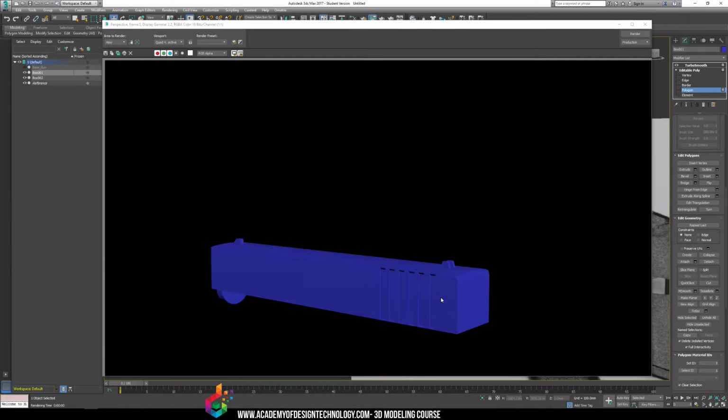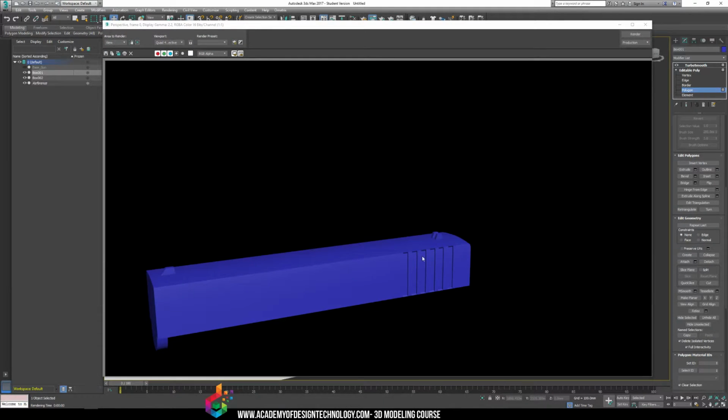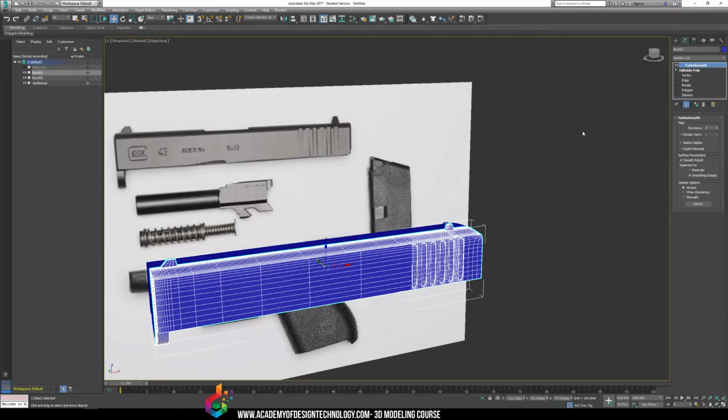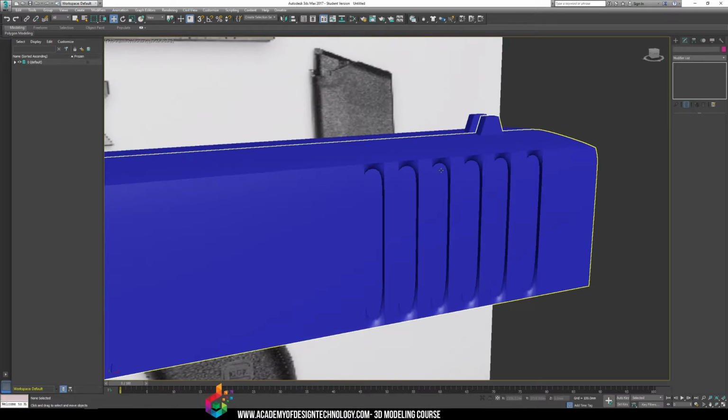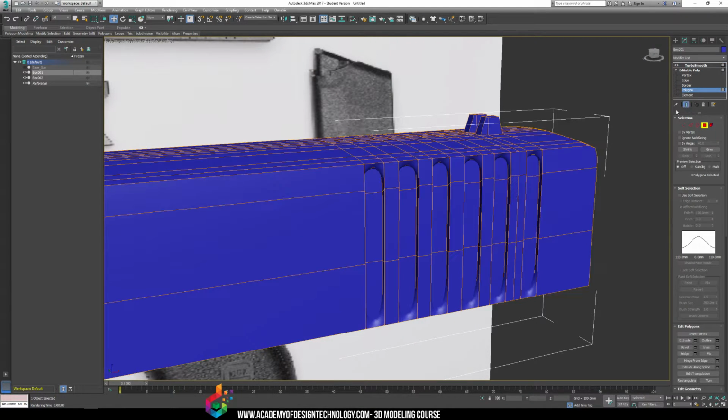Like that. And you can see I get those nice ridges in the side of the gun. Now these are on both sides of the gun, so that works for me. You're going to have to adjust your smoothing groups as well in these models, because if you turbo smooth, you're going to run into something like this. So we will have to add something like swift loops through it, or inset them just slightly. Change the smoothing group number.